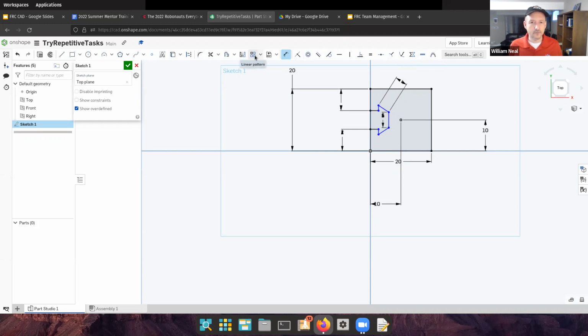Let's see what we call this, or what we can do. Linear pattern or mirror. What about a circular pattern? So it's going for a circular pattern. First, I may select the items I want to be in the circular pattern, but then I may drag this to right here. Good, I dragged that there, but I don't want it 3 times, I want it 4 times.